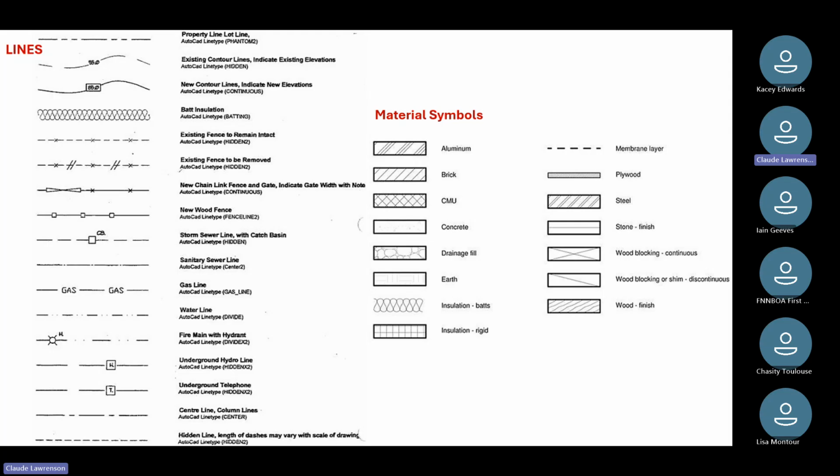If we take a look at wood blocking, solid wood members, over on the far right-hand side we see it as basically a shape with an X through it. And wood finish, the very bottom one there, is another example. It looks like it has some free-drawn lines in between the materials, which indicates a finished wood. We'll call it the designation in that particular case. So again, these are a few of the examples. There are many, many more, just to give you a quick overview of what is comprised in architectural drawings, what to see, what to expect.